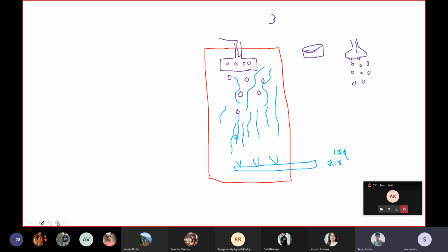The urea granules gradually settle, so that there will be less attrition between the particles. So we design the air flow rate and the droplet size such that it will get cooled down. Also, the settling behavior can be very gradual rather than just falling from the top.